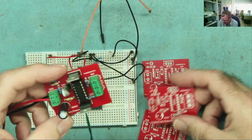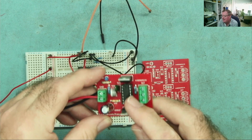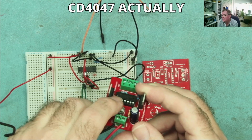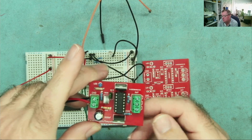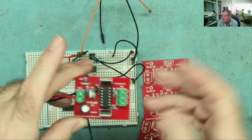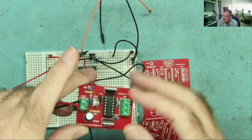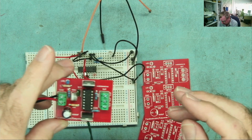So in part 1, I built this inverter to find that the outputs on this IC, CD4070, are not driving the MOSFETs. One is switched on and one is switched off. It should oscillate. But the chip is oscillating. It has an oscillator output on pin 13. It is oscillating at the expected frequency. It just isn't driving the MOSFETs from the other outputs on pins 10 and 11.